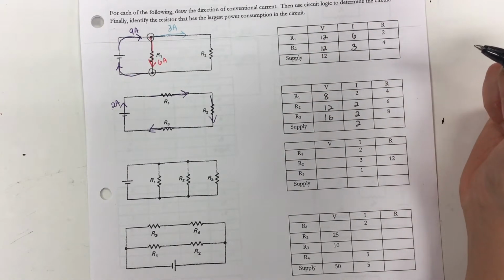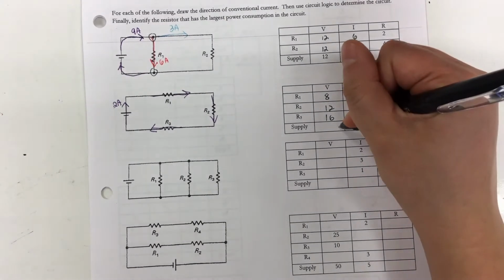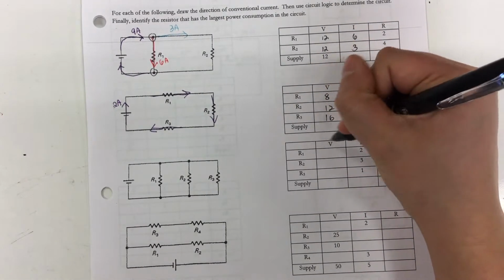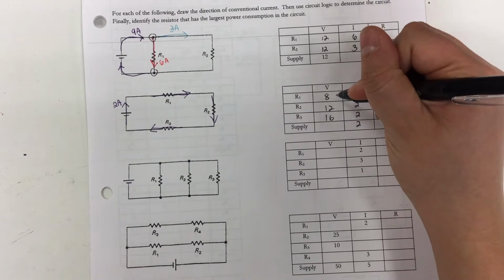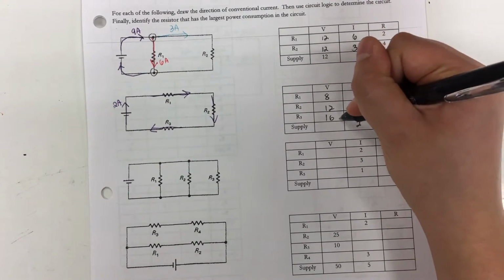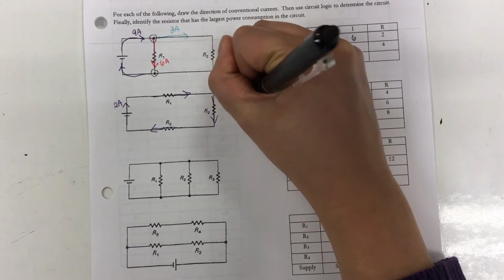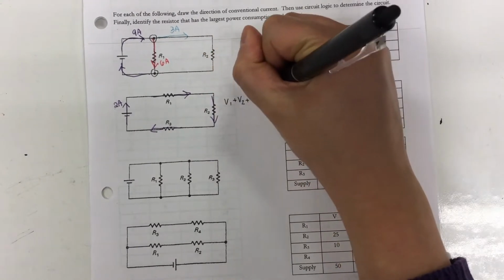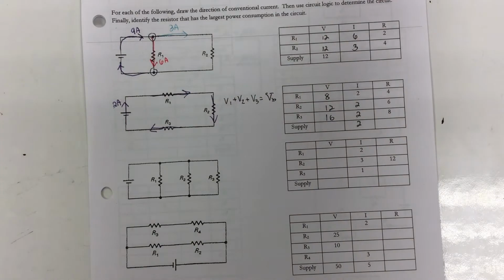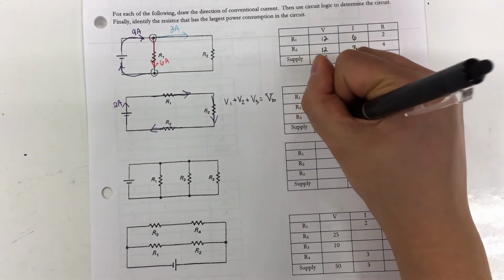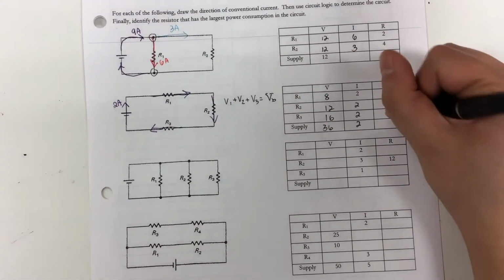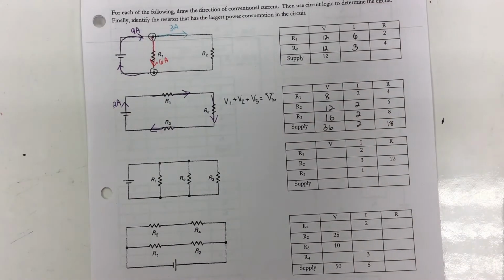And by loop rule, the supply has to give enough energy to the loop so that an electron can make it through these 3 obstacles. So, in order to make it through a loop of V1, V2, and V3, the battery must have put out enough energy to make it through. This gives the supply a total voltage of 36, requiring the equivalent resistance to be 18.